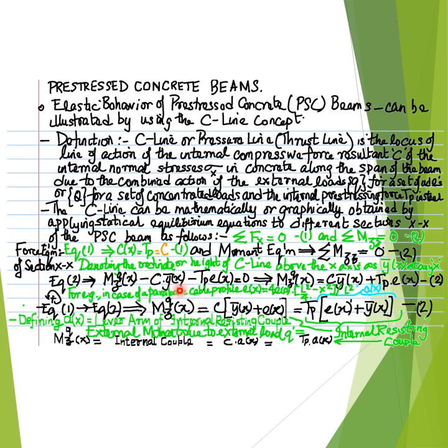since the externally applied bending moment capital M subscript Z superscript Q at any location, at all locations x, should be balanced by the internal resisting couple formed by the internal compressive force resultant C in the concrete and the internal tensile force resultant due to the pre-stressing force Tp in the steel at that location or cross section of the pre-stressed concrete beam.